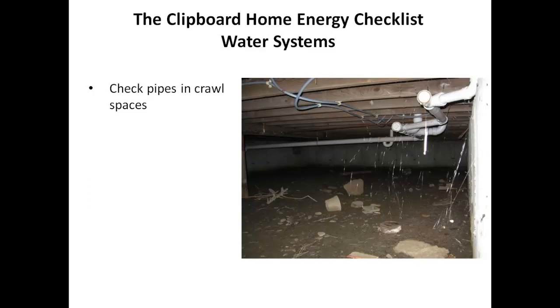There was a question about why that freezing would have happened even sooner, and that is because if they would have insulated the floor joist where the room up above is a conditioned area that gets heat, then the heat would not have been able to travel down into the crawl space, and that heat probably helped keep that pipe from freezing for some time until the temperature got so low that it couldn't.